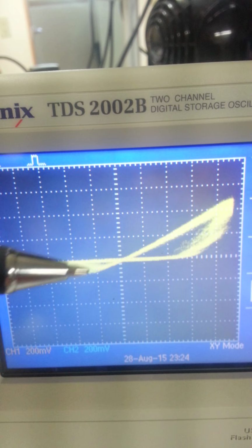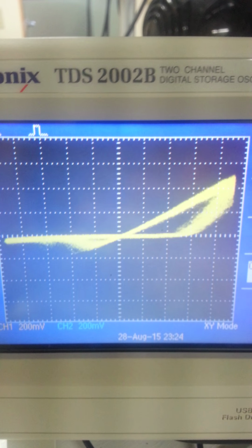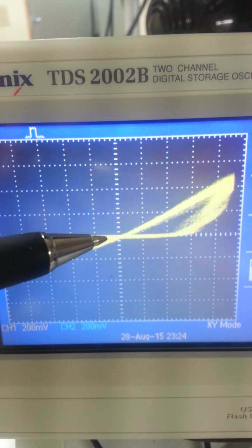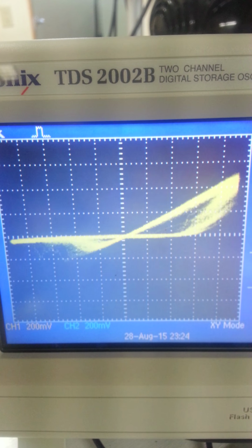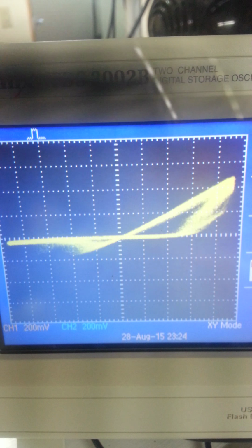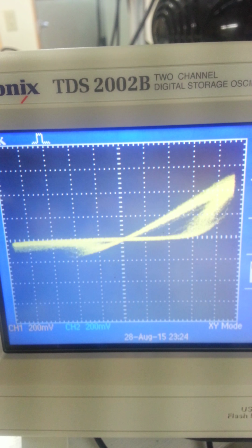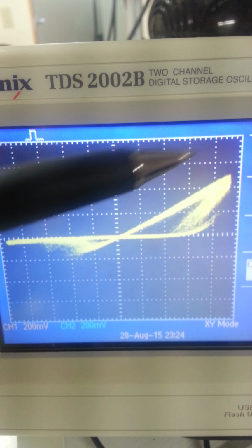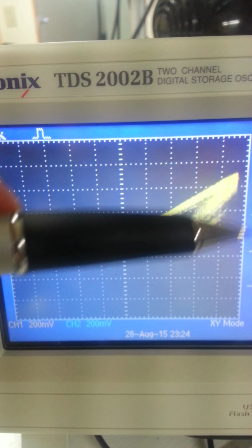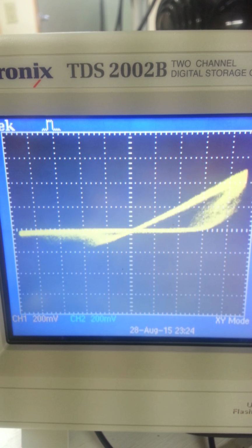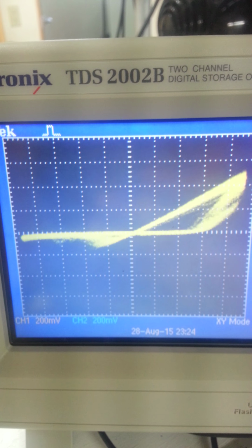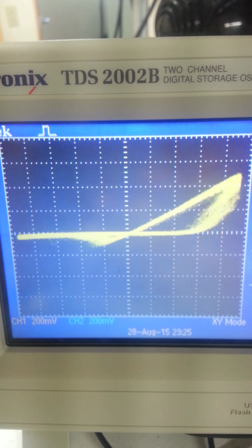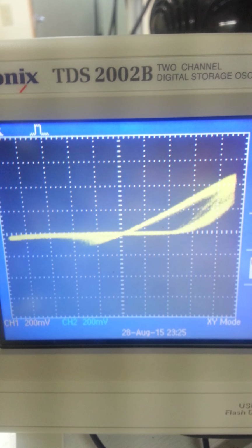As Leon Chua, the theoretical inventor of the memristor, has said, if it's pinched, it's a memristor. This is true for a number of devices. What's special about this device is that it has lots of intermediate resistance states, and it can be controllably incremented between those states in both a forward and reverse direction. In other words, it's an ideal learning device. That's it.